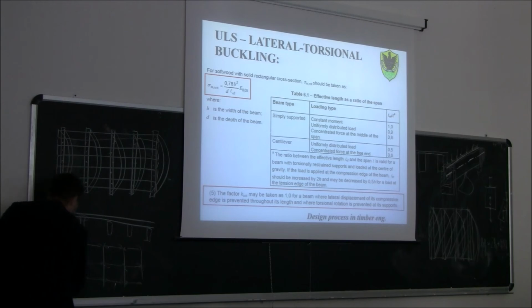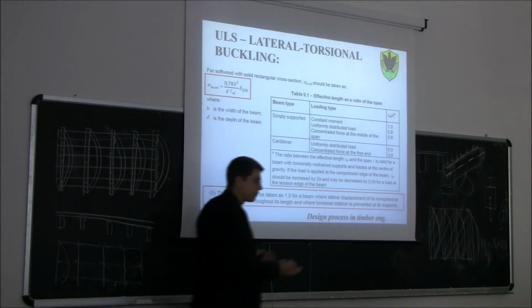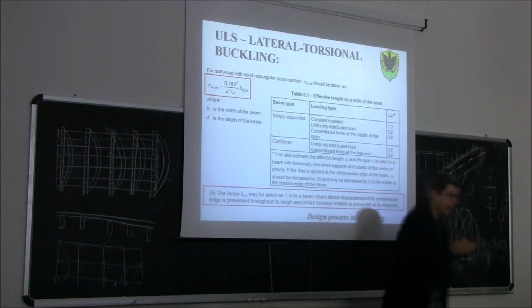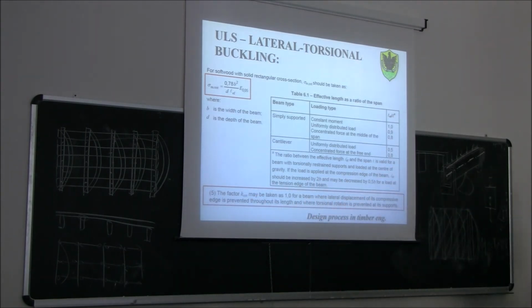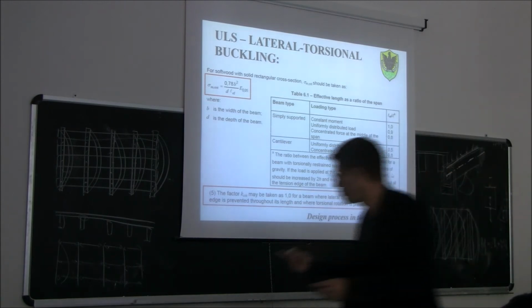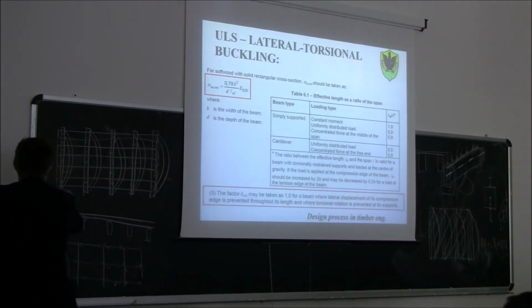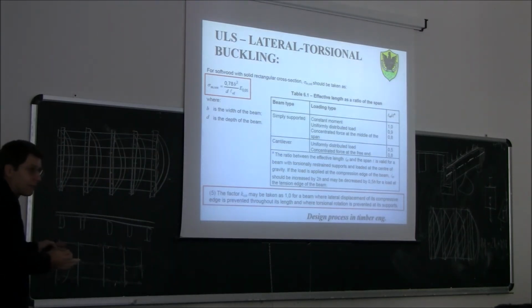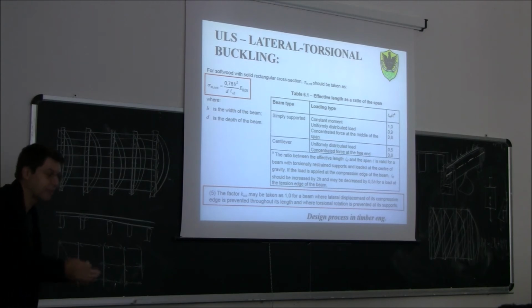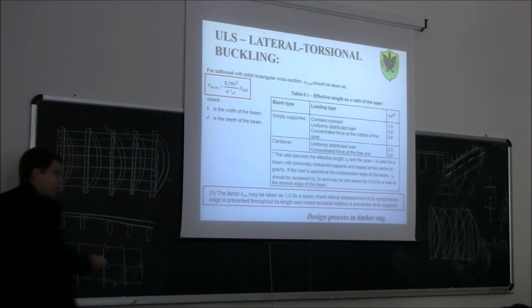Okay, so as soon as one beam buckles, all the others buckle together. Theoretically, this is the case of a very narrow board with only one nail in between. Of course, if the board becomes a bit wider, and rather than using one nail you use two, then the effect is a bit better, because the board, rather than acting only in tension and compression, can also transmit a certain bending moment. So it can also prevent this rotation a little bit.